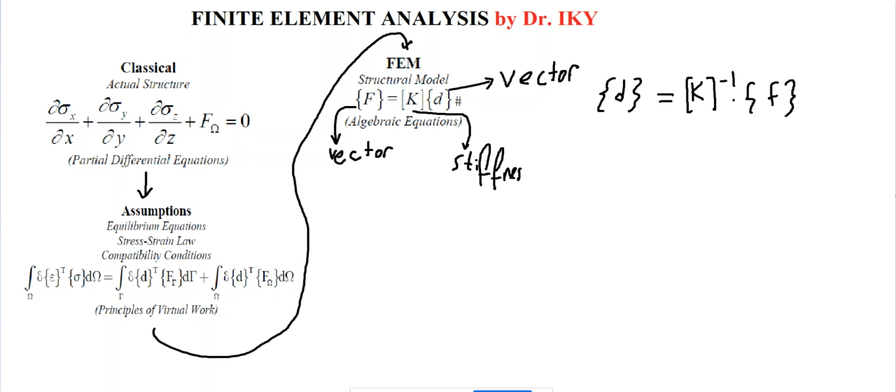Let me talk about the parameters, maybe for different cases. Let me tell you about the solid one. The property of the solid can be described by the stiffness matrix, but in fluid you will use the viscosity matrix, or for thermal solutions you will use the conductivity matrix.